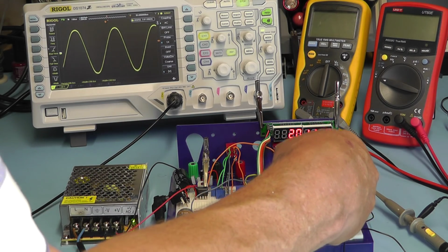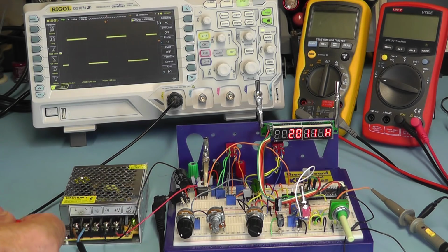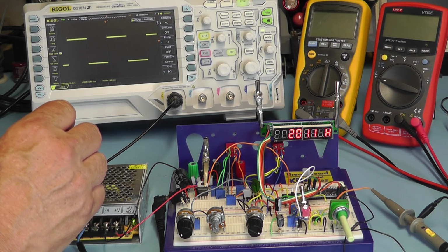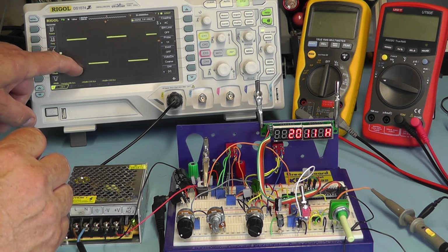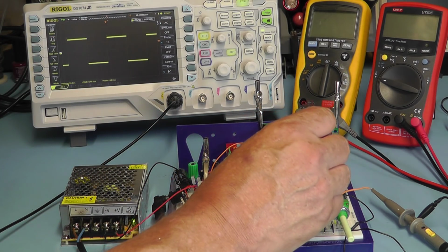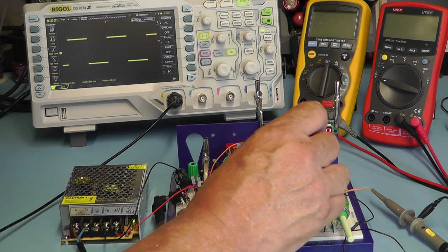Then switch to square wave, and we will try and adjust the preset there to get also 6 volts peak to peak. At the moment we've only got just less than 4 volts, so if I try and adjust the other preset,